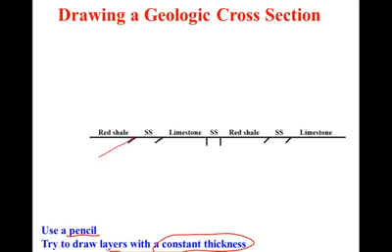Well, this sandstone, again, is dipping 30 degrees to the west. I'm going to draw dashed lines representing the part of the structure that's been eroded away, where I'm drawing it above the ground surface. Note that I've drawn my sandstone layer with a constant thickness, but I've been changing the dip direction and angle to allow it to go from 30 degrees to the west to 85 degrees to the east.